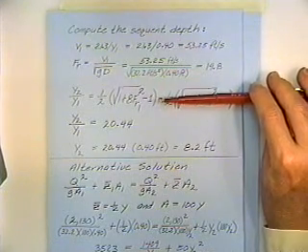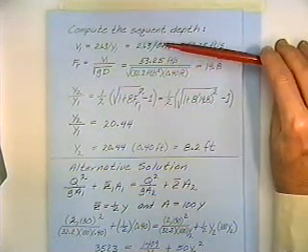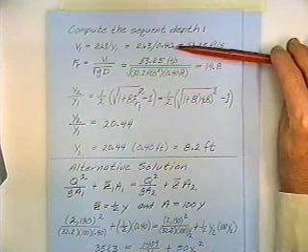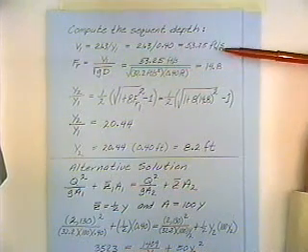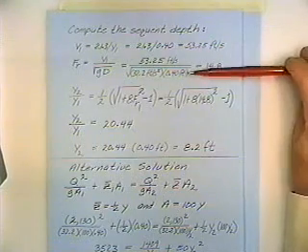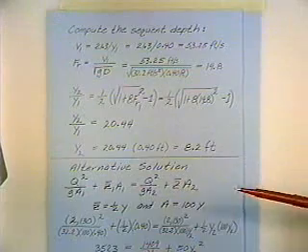That's for a rectangular channel. And so we take our depth that we just computed, plug it into the expression from the previous page to get the velocity, use the velocity to compute the Froude number, and then plug in for the Froude number.